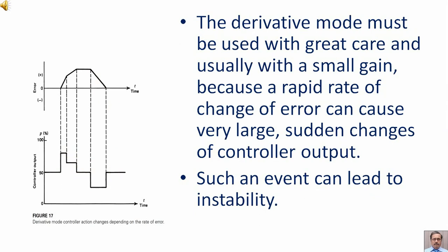The derivative mode must be used with great care and usually with a small gain, because a rapid rate of change of error can cause very large sudden changes of controller output. Such an event can lead to instability.